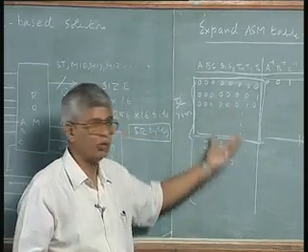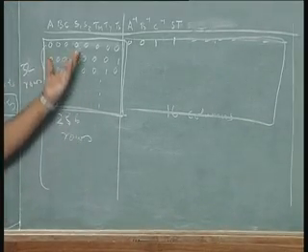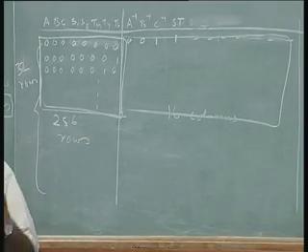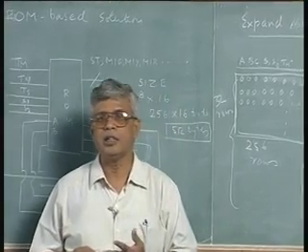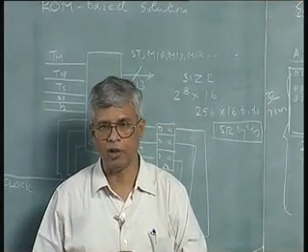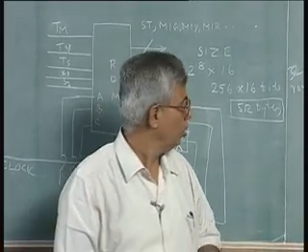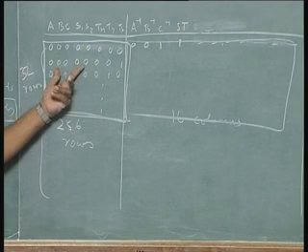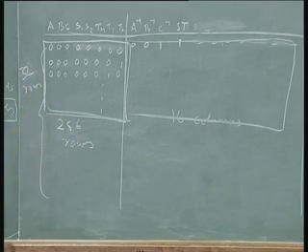Of course you do not give it in this form. A ROM table, you do in hexadecimal form. A ROM table is not written in binary because it is so huge to write. An ASM table or state table we write in binary, or a truth table we write in binary. A ROM table is generally written in hexadecimal form, so we can compress the size of the table. So this will be written as 00 hexadecimal, this is 01, this is 02, like that. So the hexadecimal ROM table will look like